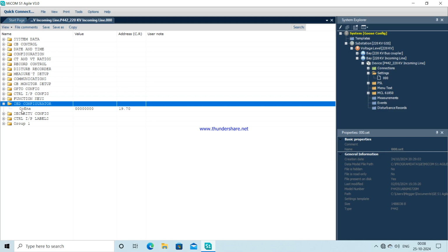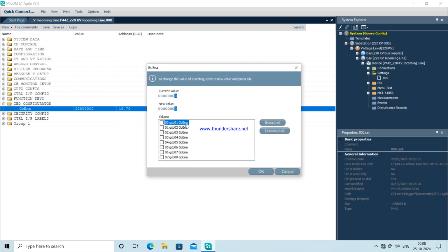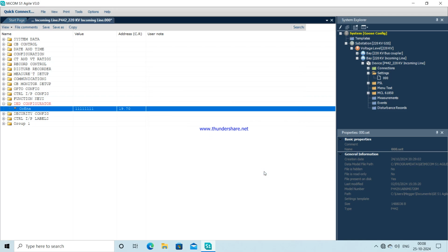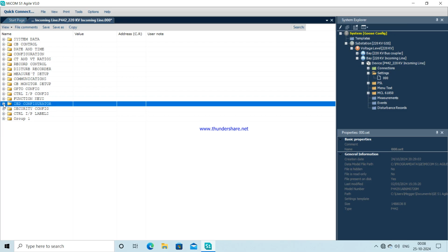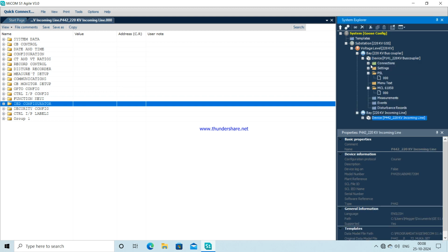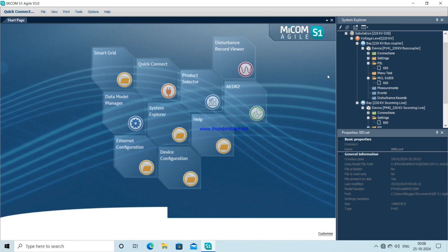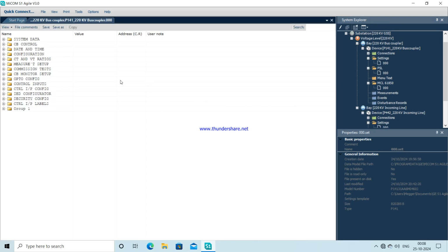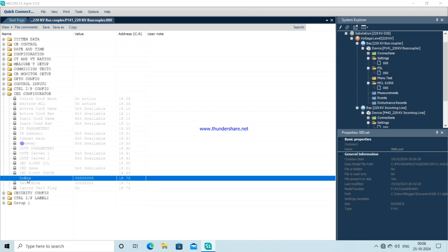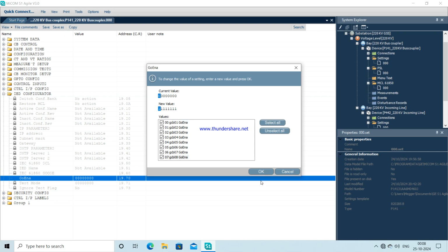It is the simplest way in which soft digital signals can be transferred from one relay to another, and the beauty of Goose communication in the IEC 61850 protocol is that it can be used with any relay, irrespective of make, whether it is a Siemens relay, a GE relay or an ABB relay, all can be used interchangeably.